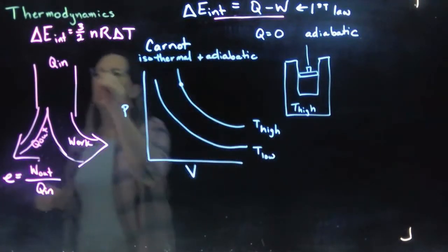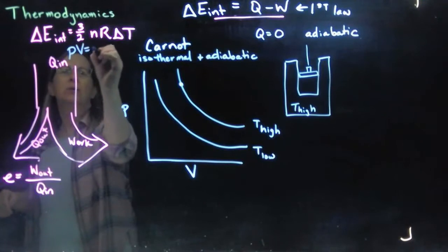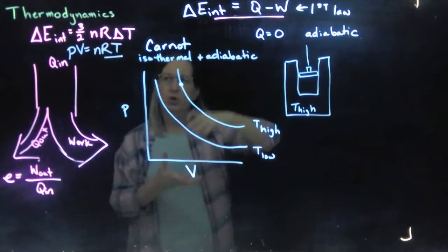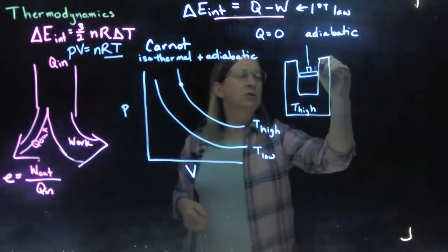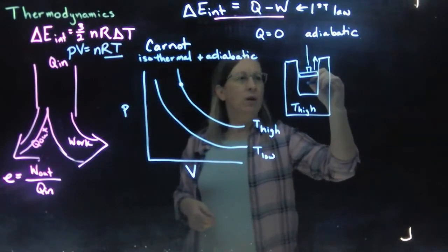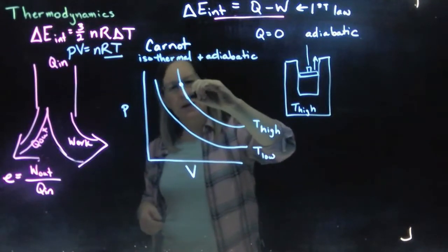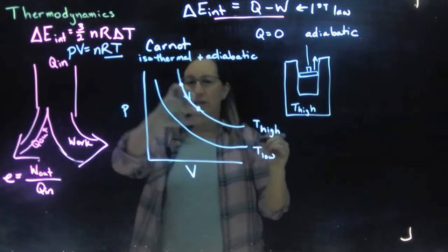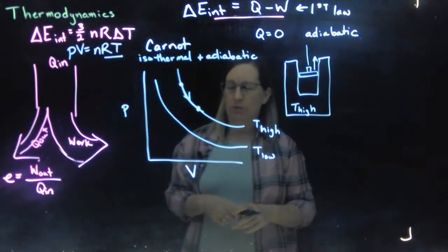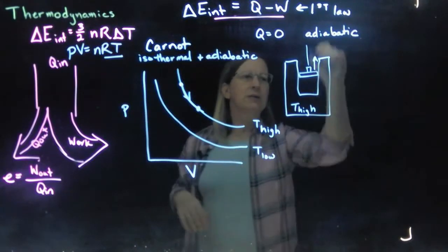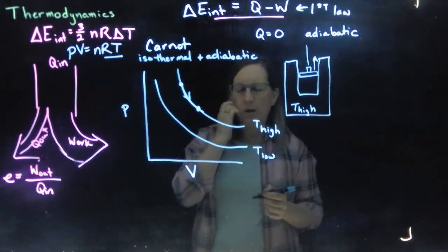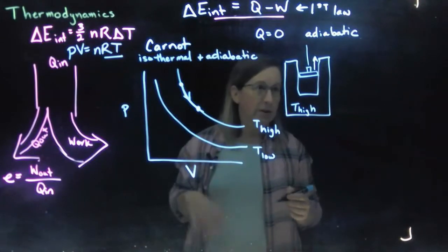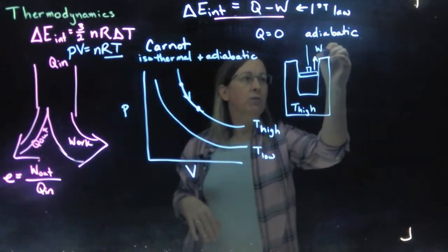So let's think of PV equals nRT. The temperature stays constant. So this expands, right? So this goes up. We've got positive work. It expands. And as it does so, the pressure is going to have to decrease if we're going to stay on this isotherm. So that's step A. So this increases up. Then what we're going to do is have even more expansion, more work. So this is the work for A.